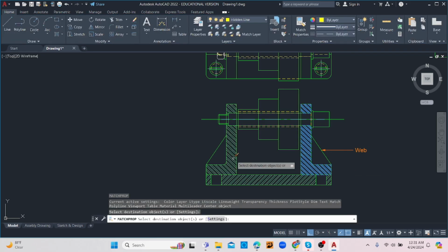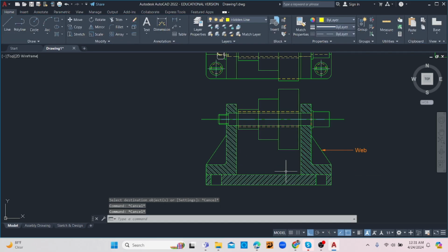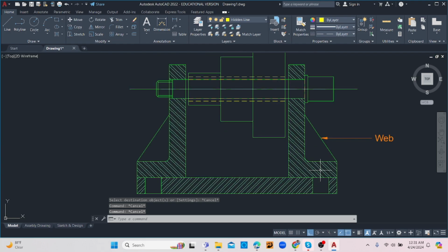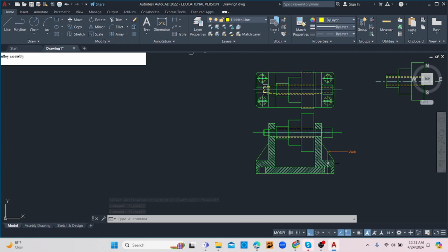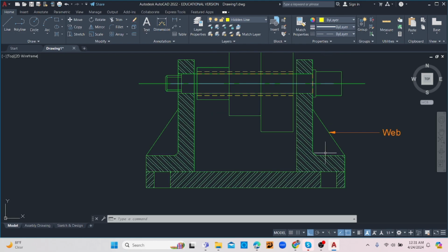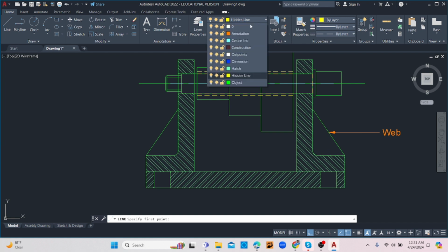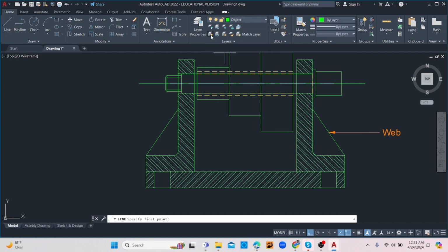Alright, now please bear in mind that this here had a hole in it. That's the, what do you call this, the bracket. So what I'll simply do, I'll draw a line, so I don't want to confuse it, up from here to there, because we forgot to add the hole on the elevation view. So we're adding it now, and we're going to trim out the hatch that we have inside there.